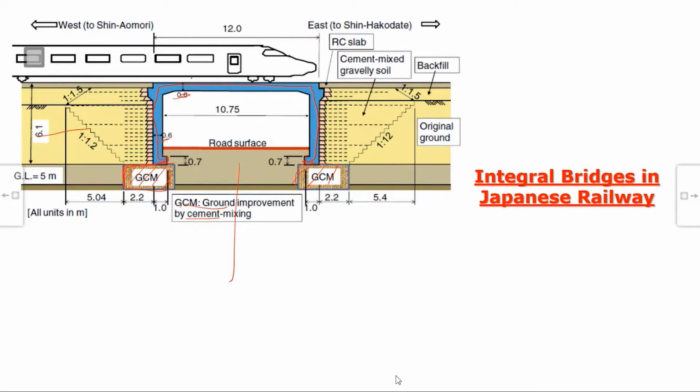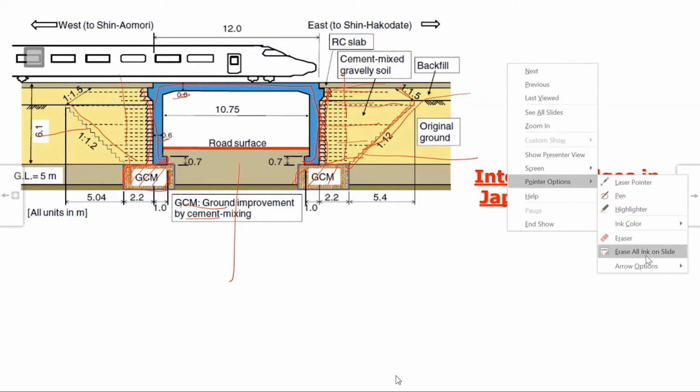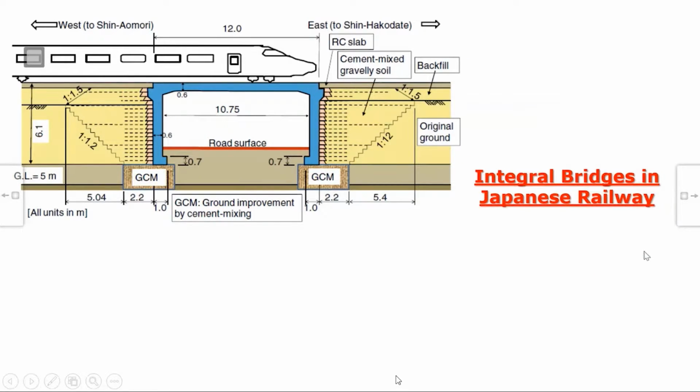And this is a single cast thing, and for the abutment, this is the reinforcement pattern in a triangular fashion like this. Some reinforcement goes up to the end of this triangle, every 4th, 5th or 6th. And this is drain. And this is your select soil or reinforced fill, and behind this is the original backfill. So now you can see how lean and easily constructible these structures are. Again, they have been constructing using the principle of reinforced earth.